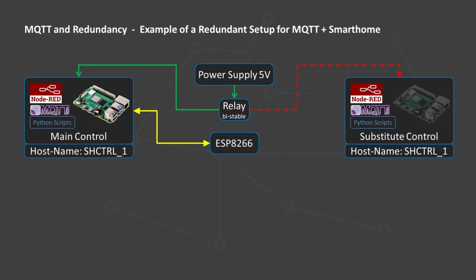How did I make my system redundant? In my professional life, I am almost paranoid when it comes to functional safety. I work on complex electronic architectures in the automotive industry, and there we have very strong requirements. In my system setup, I have established full redundancy in the following rather simple way. It not only covers the MQTT broker, but also the entire home automation control system, which is mainly running on Node-RED and a few Python scripts. The dashboard currently is created by using Node-RED also. I have no other application running, such as Home Assistant or I/O broker or whatever else.